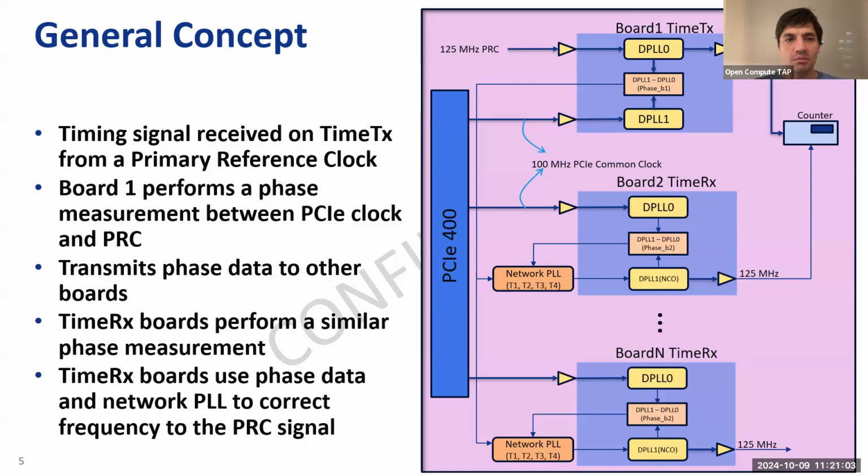Yes, I agree. And then in terms of the necessary hardware, is there anything more than the existing thing? Basically the diff pair for the clock, and you have one PCIe lane minimum. There's nothing else you need. Is that correct? Absolutely. Simon can comment on that, but there is no extra hardware. I think you would need a relatively stable oscillator on these boards. Good oscillators would help, but no, it's just a PLL.